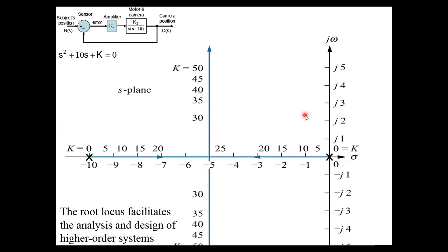Finally, since the root locus never crosses over into the right half plane, the system is always stable regardless of the value of gain and can never break into sinusoidal oscillation. These conclusions for such a simple system may appear trivial. What we are about to see is that the analysis is applicable to systems of order higher than 2. The root locus will allow us to make that association and will become an important technique in the analysis and design of higher order systems.